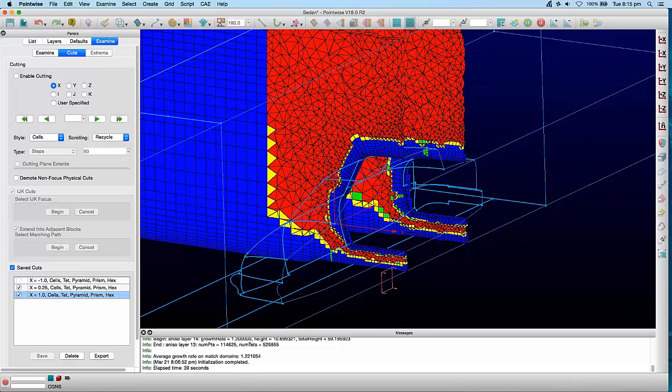So yeah, Scott started with y+ 1 Spalart-Allmaras, and he's still using Spalart-Allmaras, but now with a y+ around 30, and having much less runtime because he didn't change the size of the computer, but he reduced the mesh size significantly. Yeah, that's a good question. Thanks, Joan.